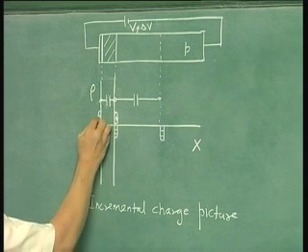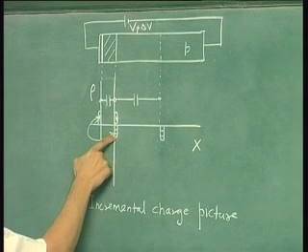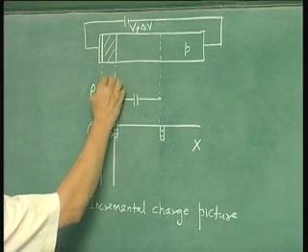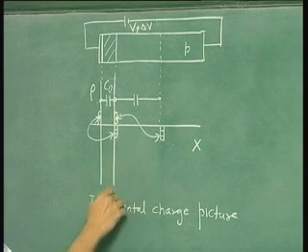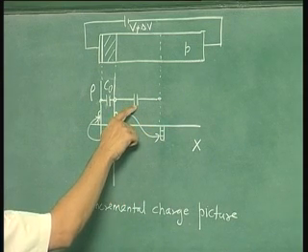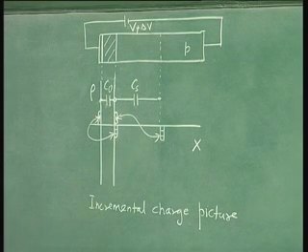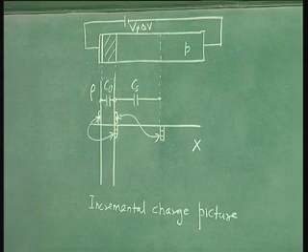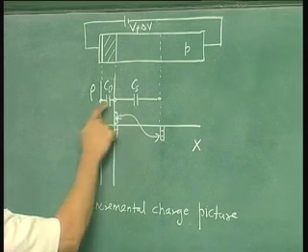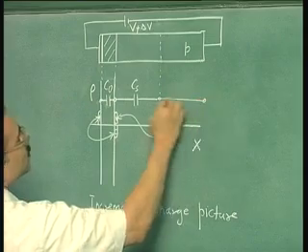But now supposing you pair up these two charges, they amount to a capacitance equal to the oxide capacitance, C0. Then you pair up these two charges, they amount to a capacitance here. This is the semiconductor or depletion region capacitance. Therefore, the capacitance of the MOS capacitor in depletion is a series combination of these two, between this point and this point, which is the same as this point.